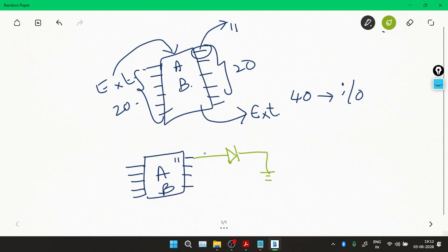Of course, when you go for practical implementation, you would keep a resistor here, or else a resistor is not needed, because this Arduino board by default gives an output voltage of 5 volts. It takes 5 volts as an input and gives 5 volts as an output also. So there is no need for a resistor between the Arduino board and the LED, but it's up to you. You can keep it. So this is the setup of our experiment, a diagrammatic representation.